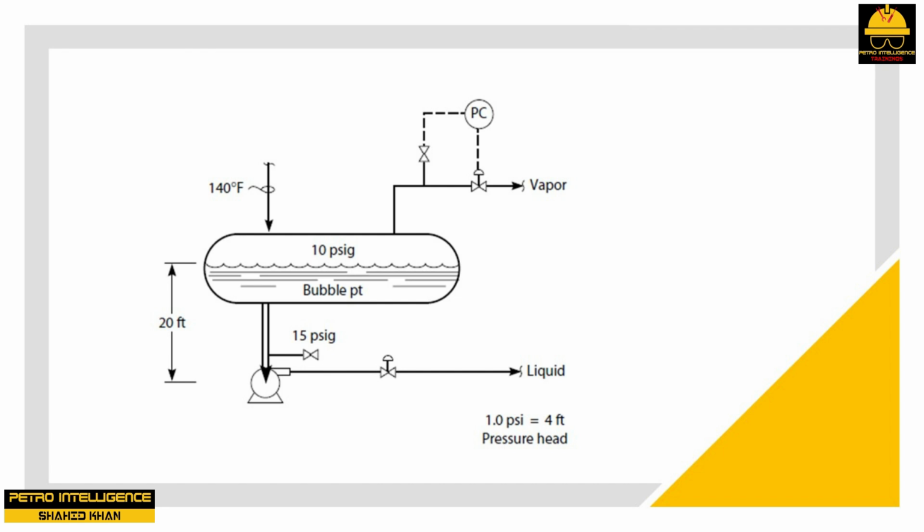The temporary difference in the suction pressure between 14 and 12 psig is due to a 2 psi conversion of pressure to velocity or kinetic energy. To review, all the energy needed to accelerate the liquid to the suction of a pump comes from the pump's suction pressure. None of this energy comes from the pump itself. Or, as one clever operator at the refinery explained to me, pumps push, but they do not suck.